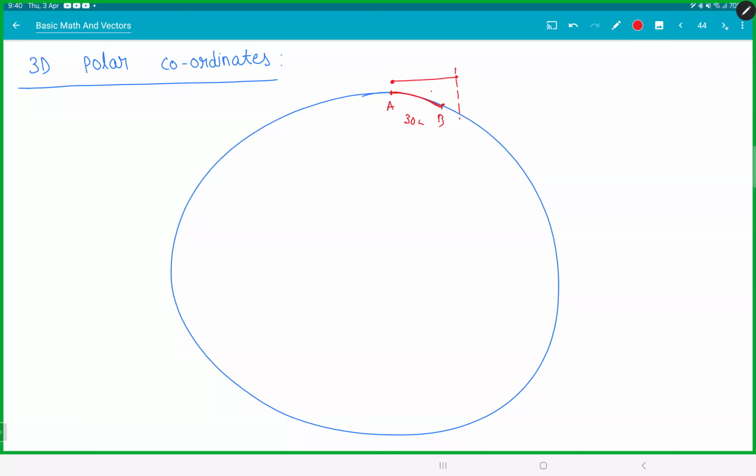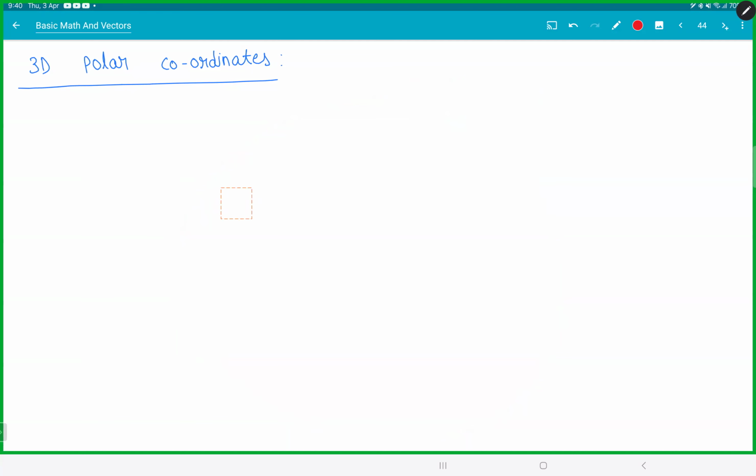Especially when you're going long distances, if you see this entire programming that you do on drones, you have to do it in 3D coordinates. For short distances, it is okay. But once you are traveling at distances of 10, 15, 20, 30 kilometers, the Earth's curvature will start mattering. Clear? So you actually lose precision. So 3D coordinates do matter. So how do we actually tackle 3D coordinates?